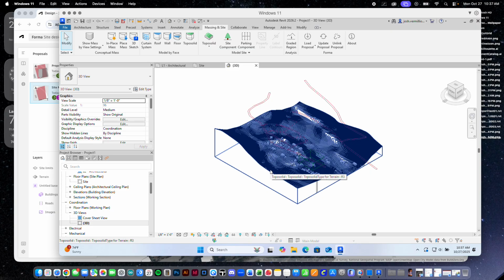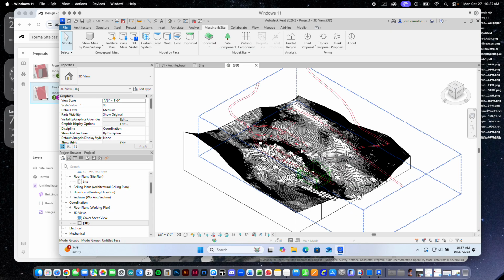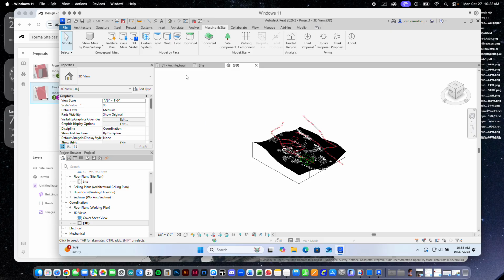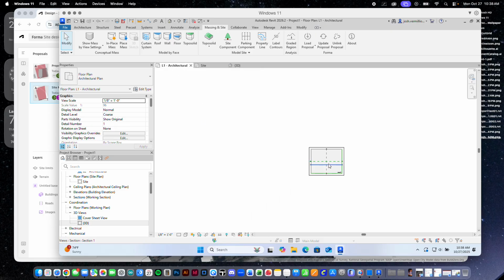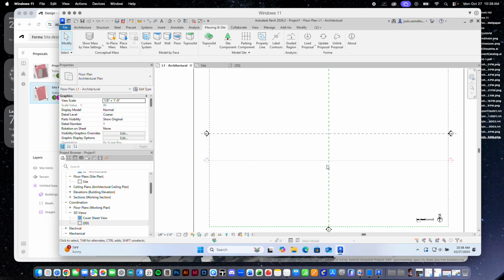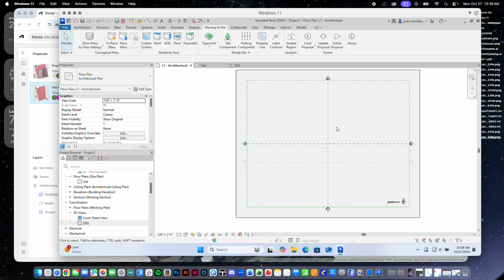Revit. Oh, here it is. Okay. So, a couple of things you might notice, right? If I go to level 1 floor plan, all I see is a gray fill. In other words, level 1 is occupying some place in this section that's cutting through mountain, and our site's probably both higher and way off in space from where this scope box has us set, okay?